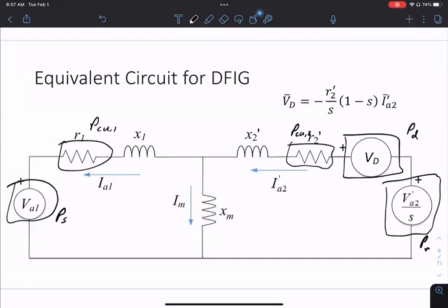Okay. So again, we're going to go back to the induction generator equations, and update all the equations by accounting for this additional term here. So we have all those equations before. When we had the added resistance for type 2, we added some equations. So here, when we account for the added voltage, first I'm going to add another term to all these equations.